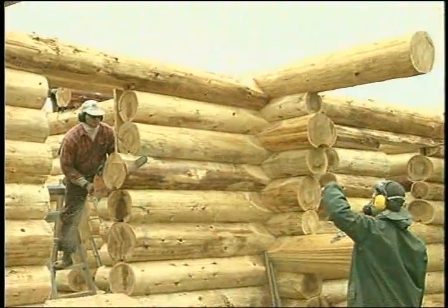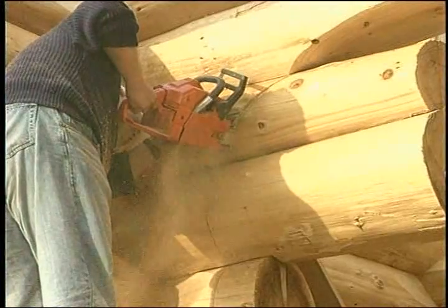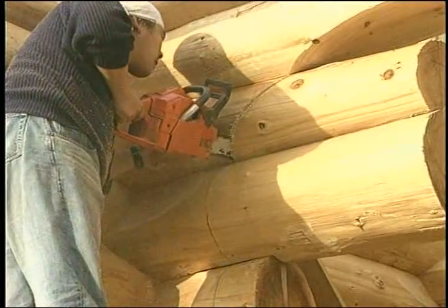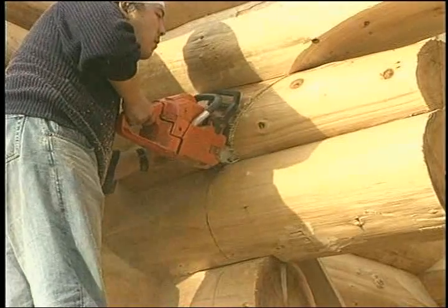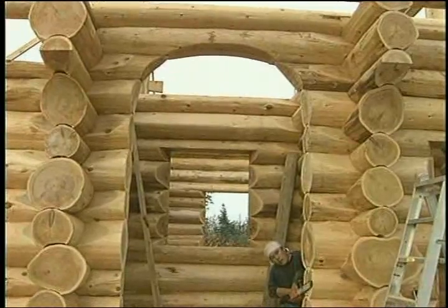You have only 3 more jobs to complete to finish your log work. 1. Cut out any archways. Be careful to keep the saw at right angles to the wall. Make a practice cut at least 6 inches inside the final cut line if you've not done this before.